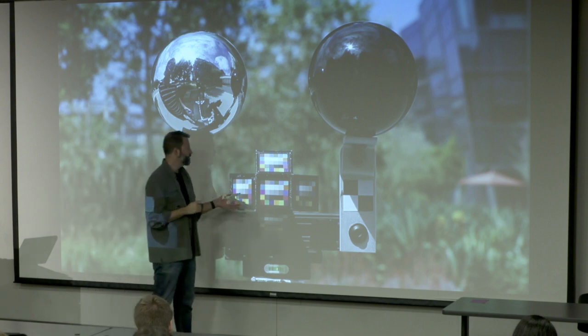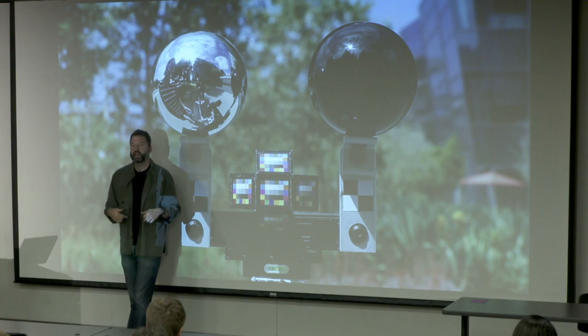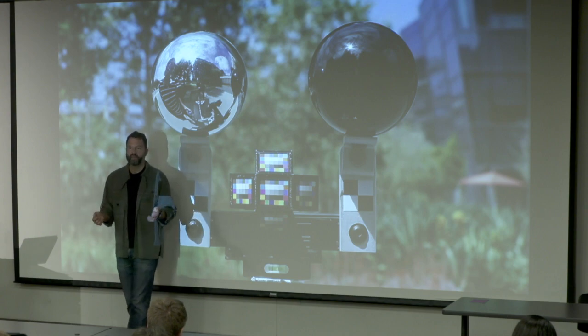And what we realized is that if we simply take the color chart, put it in the light stage, and see how the color chart looks to our camera under each one of the LEDs, this forms the basis that we want to match. We can drive the LEDs to optimally match the color chart's appearance any way that we want, just by solving a non-negative least squares problem to figure out how much of the red LED, the amber, green, cyan, blue, and white that we need to turn on to make a color chart look the same.